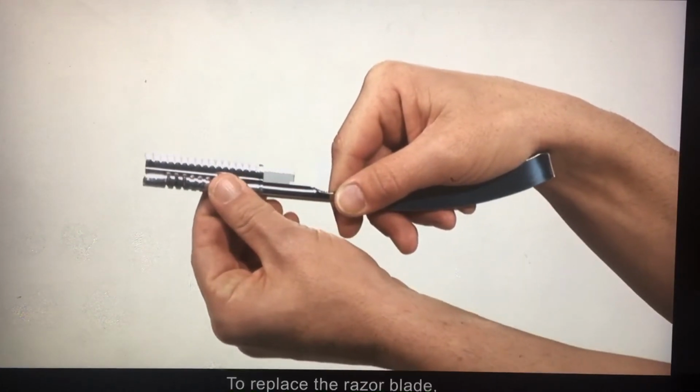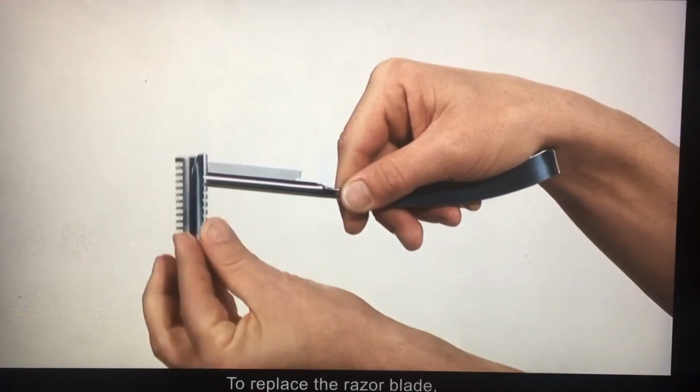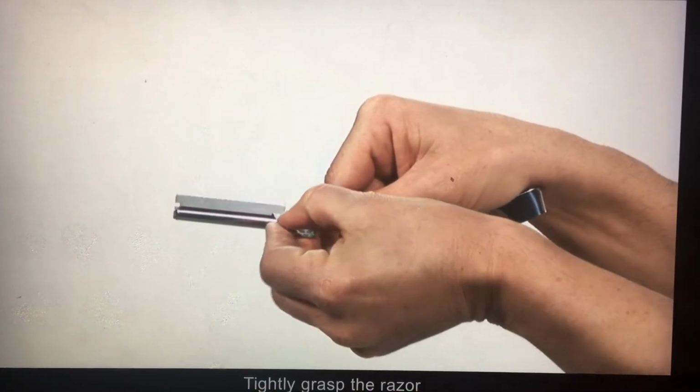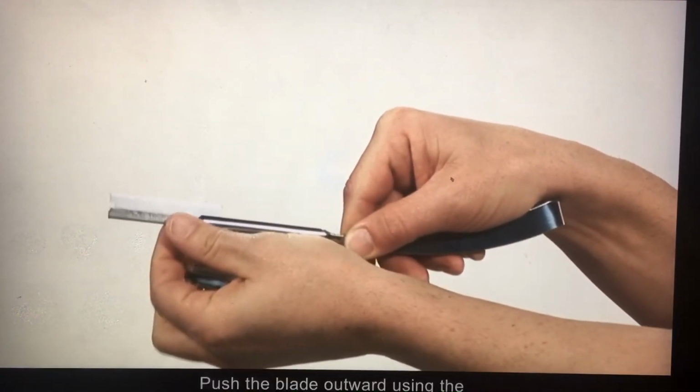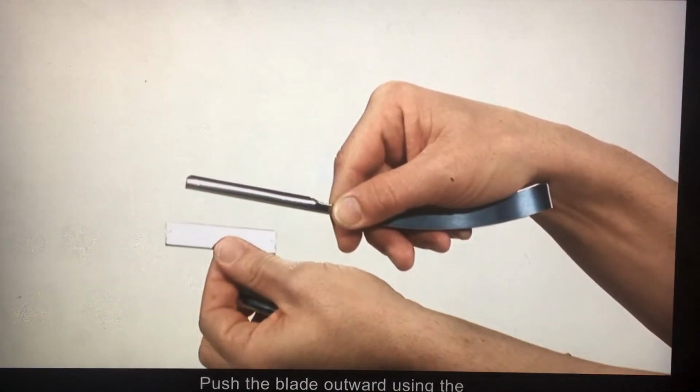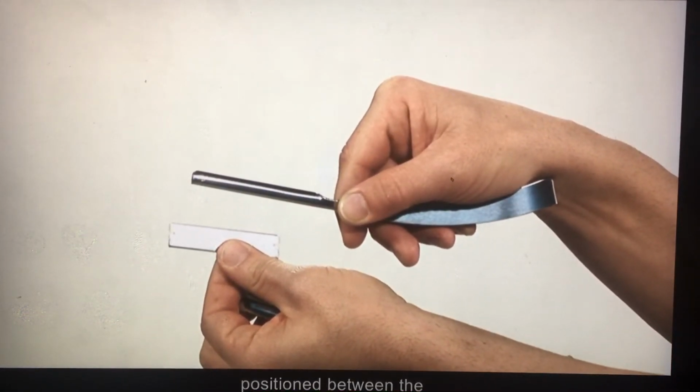To replace the razor blade, start with a cutting edge facing upward. Tightly grasp the razor handle and shank, then slide the guard out. Push the blade outward using the shank with the razor blade positioned between the teeth of the guard. Carefully remove the blade with your thumb and index finger.